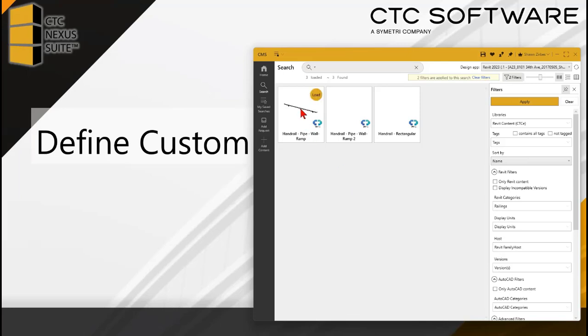Now, the little mounting object here, the little wall bracket, that is an RFA, and that can be used within a railing. But the railing overall, its whole configuration, when we're talking about a system family in Revit, there is no preview control that I can get for a railing that's been drawn in Revit, or that has a family in Revit that's a system family.